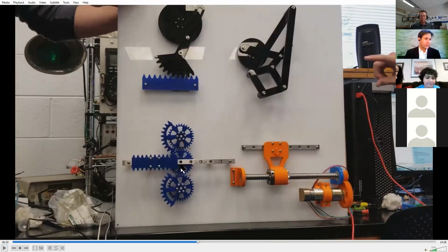it's a lot more inexpensive and more reliable if you do something like this bottom right one, which is just using a DC motor and a quadrature encoder on a ball screw to mimic these motions. So this is actually meant to be a display for a science museum in Richmond, where you basically just choose which one of these three you want, and this system could make all three of these.